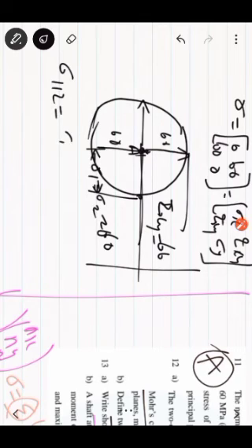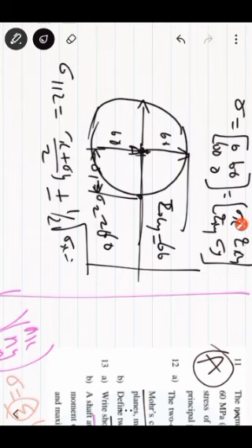Sigma 1, sigma 2 is equal to sigma x plus sigma y by 2 plus or minus 1 by 2 into square root of sigma x minus sigma y the whole square plus 4 times tau xy square.